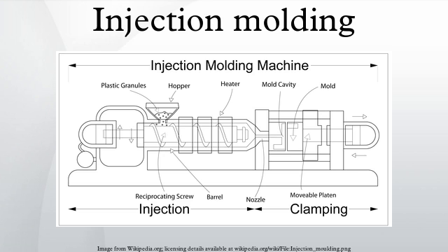To prevent spikes in pressure, the process normally utilizes a transfer position corresponding to a 95–98% full cavity where the screw shifts from a constant velocity to a constant pressure control. Often injection times are well under 1 second.